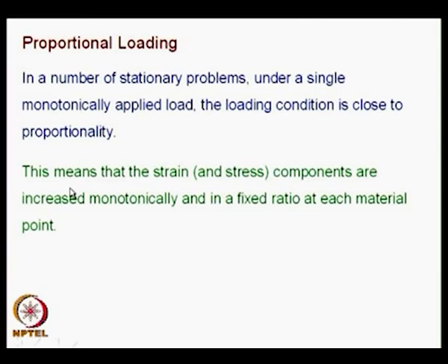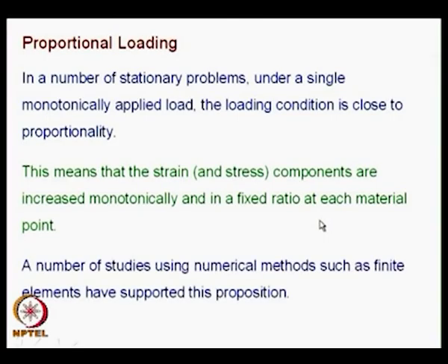This means that the strain and stress components are increased monotonically and in a fixed ratio at each material point. And this is how you justify your approximation. A number of studies using numerical methods such as finite elements have supported this proposition.